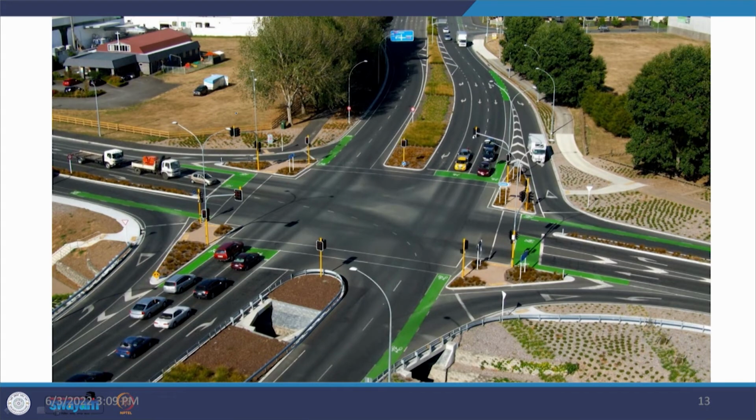So, here there is again a case where even the various types of priorities have been set. Say that this green color is for bicycle. So, the priority is given to a bicyclist, and those bicyclists can come and stand in front of the vehicles. So, these vehicles which are stopping in this area, actually they can be challaned for it. So, that is the penalization which can be there. You can see again the chevrons being marked, the give way markings are there.